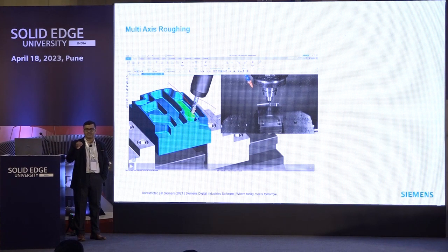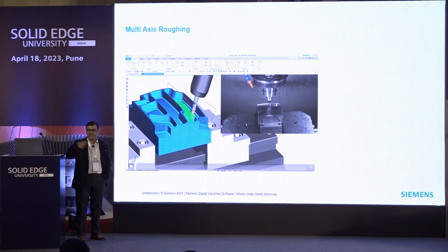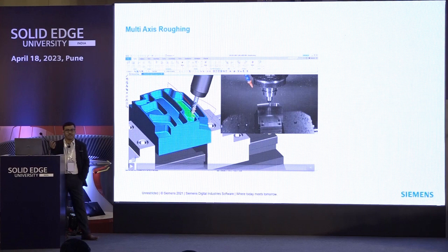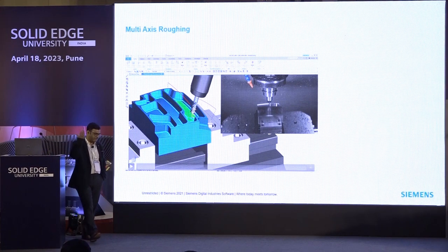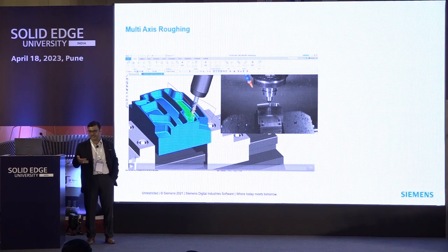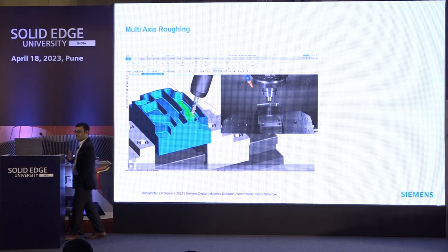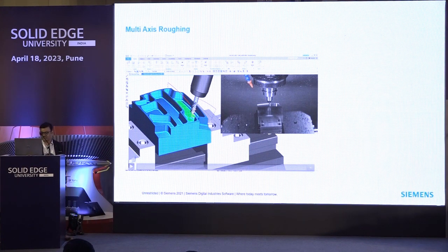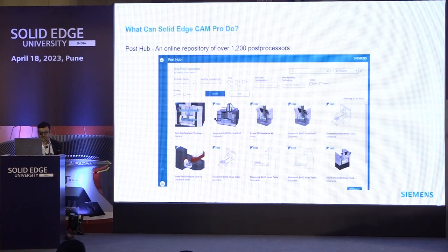Let's say once you take the toolpath, you can increase the feed rate, decrease the feed rate, depending on the cutter load condition. All that can be done digitally. So you don't need to go to third-party software to optimize the toolpath. Increasing and decreasing the feed rate is all by default. So I suggest you go ahead and optimize the toolpath depending on the cutter load condition.